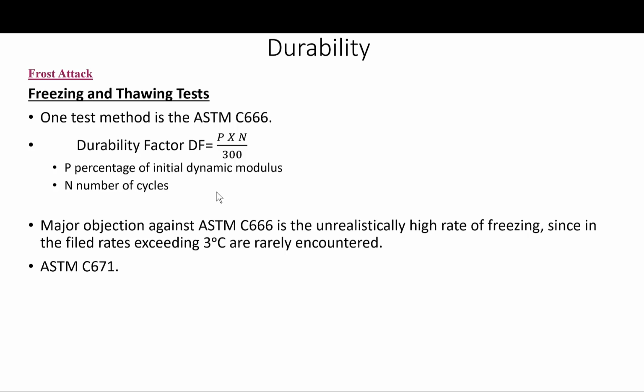Okay, so freezing can be done while the specimen is immersed in water, according to procedure A of the standard, or in air according to procedure B, because we have two different procedures prescribed in that standard. But in both cases, it is thawed in water.